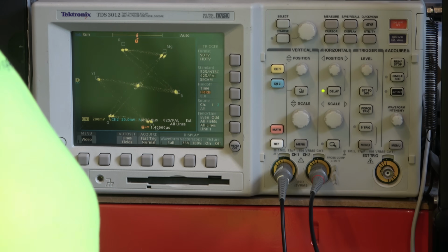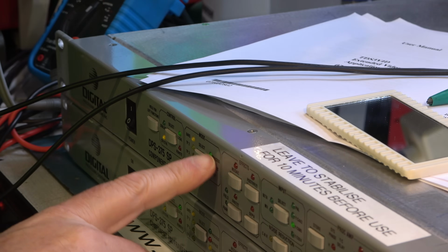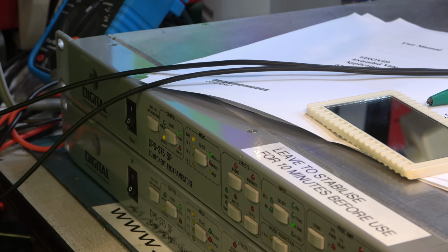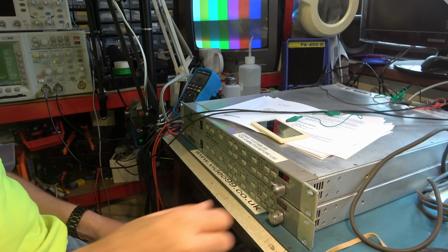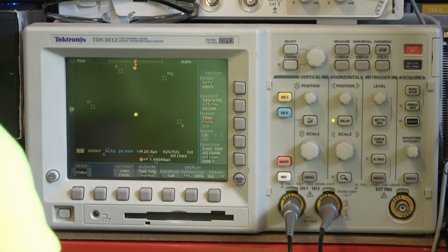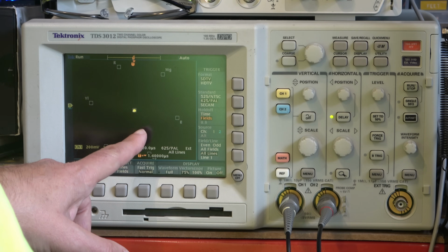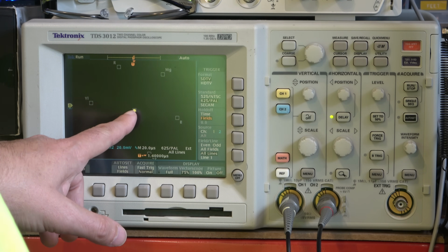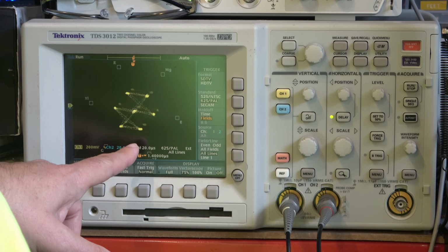If I now adjust some of the controls, so we're in process, I should be able to set chroma level and wind it down. And we'll see that on the monitor. All the colour should disappear, yep. And indeed, we see that here. Still got the noise on it, but it's all on the no chroma position. And if I turn the colour back up again, out it goes.